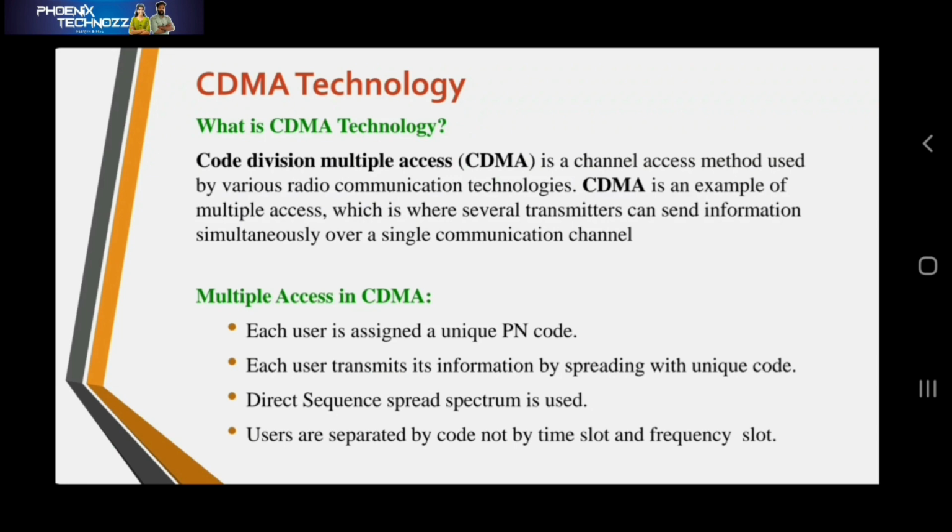Different orthogonal codes can be allocated to different users for accessing the communication resource over the entire spectrum and the entire duration. CDMA technology uses a code known as a spreading code, and these codes are orthogonal to each other, so it is possible to select a signal with a given code in the presence of many other signals with different orthogonal codes.